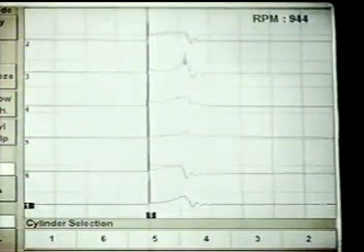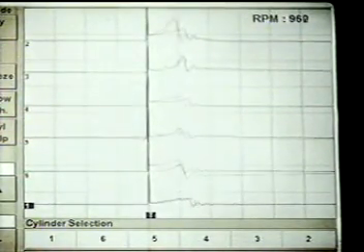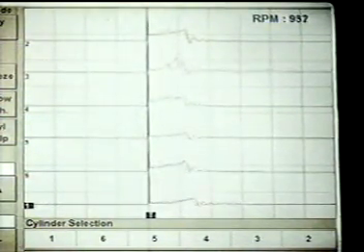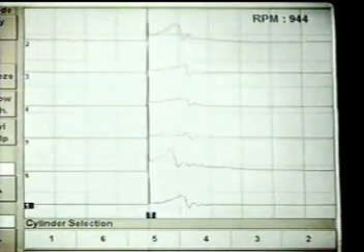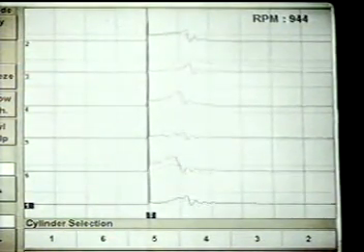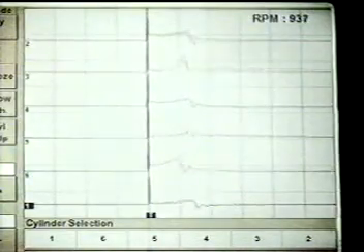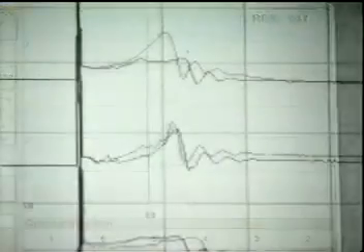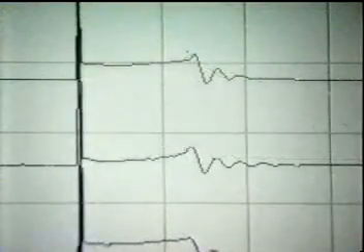We've got a GM 3.8 in here with a rough idle. We have no idea what the problem is. We did, in fact, look at a parade pattern, and everything looked normal. So, as you can see on the scope, we have shifted to the raster pattern so that we can focus on the spark line. What I want you to do is focus on all the spark lines, but in particular, I want you to focus on cylinder number 3, which is actually the second one from the top.